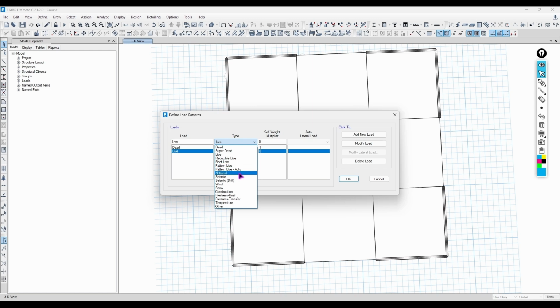Then you have a bunch of different stuff, and then you have the seismic load, which is defined in the x direction and the y direction, the wind load, the snow load, and the construction load. When you're doing the construction, you're working with formworks, machines, and men, which is more than, let's say, the family the floor is going to hold, say 4 families. Each family has 5 members, so we're talking about 20 people. Now when you are constructing, you might have 50 workers on the floor, so that's taken into consideration if you want to be really conservative.